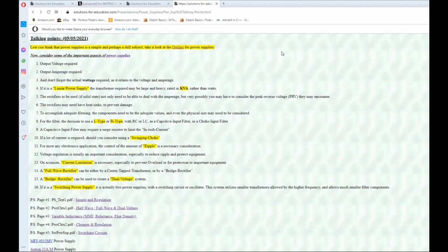In transformers, they always had laminations to reduce the eddy currents, and eddy currents at radio frequencies could not be tolerated. So they went to powdered iron, which was moved up or down for tuning. That was because of the frequency. At higher frequencies, eddy currents started being a real problem.